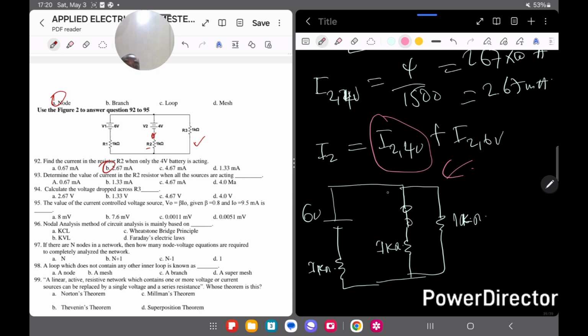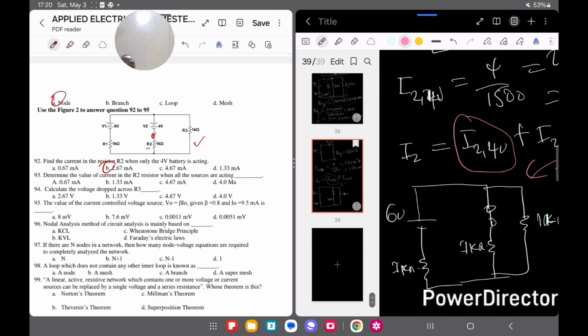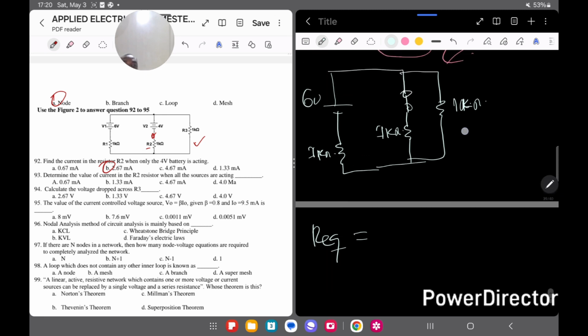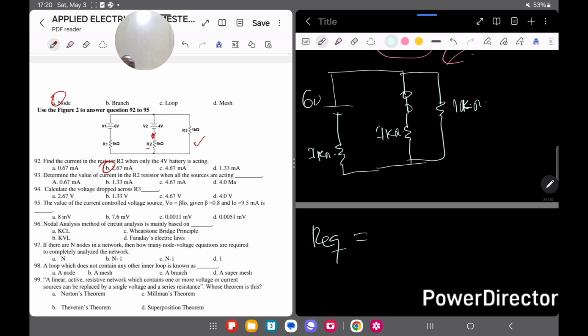So that means that here the equivalent resistance, they are all 1 kilo ohm, and you see that you get the same answer that we got. So here the equivalent resistance too is going to be equal to this. Again, these two are what? In parallel, so meaning we get 1000 ohms in parallel with another 1000 ohms, giving 500. Then they are in series with 1000. So I don't have to do this again, 500 ohms.